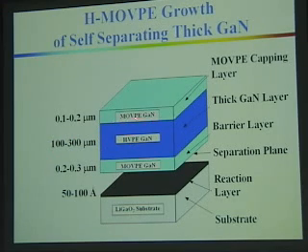We discovered, however, the surface that we would grow there was very rough. We also discovered that that surface was very reactive and thermally unstable. As a result, by chance, we grew a capping MOCVD layer of gallium nitride, and were able to recover surface smoothness and thermal stability. And I'll tell you a little bit why. But that's our basic process. So I'm going to step through these and just give you a few results at each step.